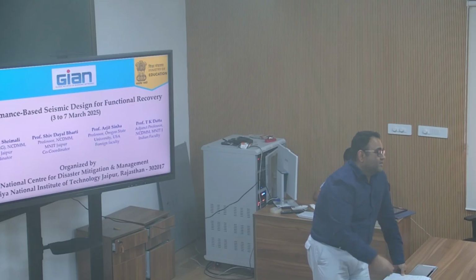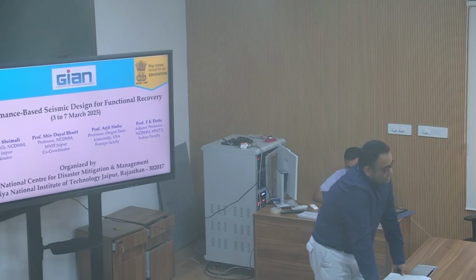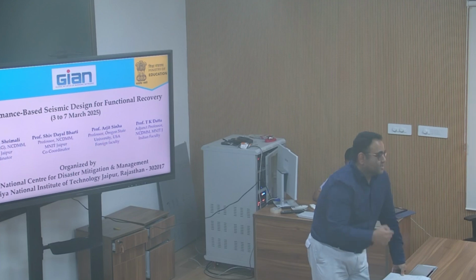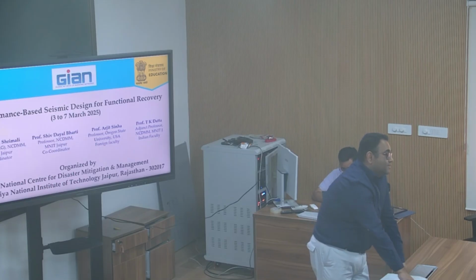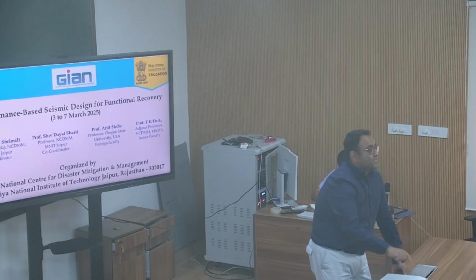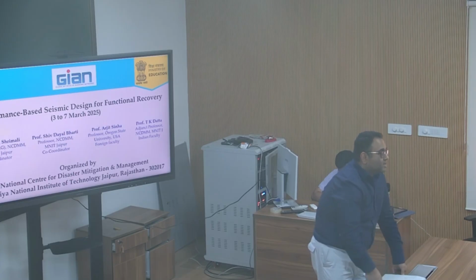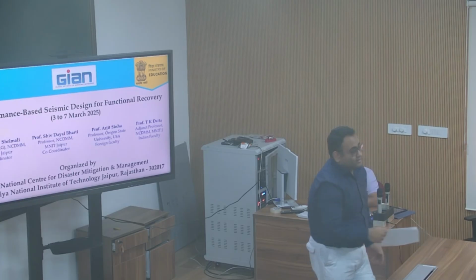So then we have to go for iteration again. Yes. That's the step we're probably going to talk about on Friday: it is an iterative process. If your concrete does not match up, then it's an iterative process. Generally, you start with a quite high grade of concrete anyways, because everything else is capacity design. So you need to design everything else in a much more elastic way, so you end up using a high grade of concrete. But that's a great question.